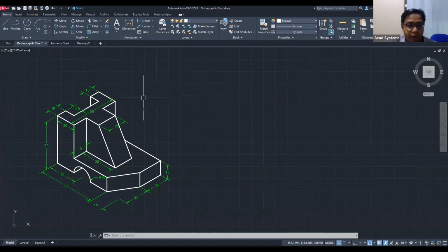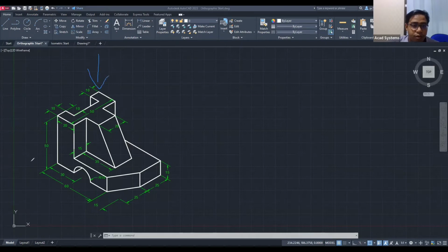So let's say what I have here is the sample from the isometric view, and what I'm going to do is take some of this information and create a few views which represent the top view, the front view, and also the right view. So basically, I'm going to start drawing from the front view, and then I'm going to create the side view and also the top view from here. So basically, this is the particular view that I'm going to take out and create. So with this, we can start by creating the first view first. Let me just clear everything.